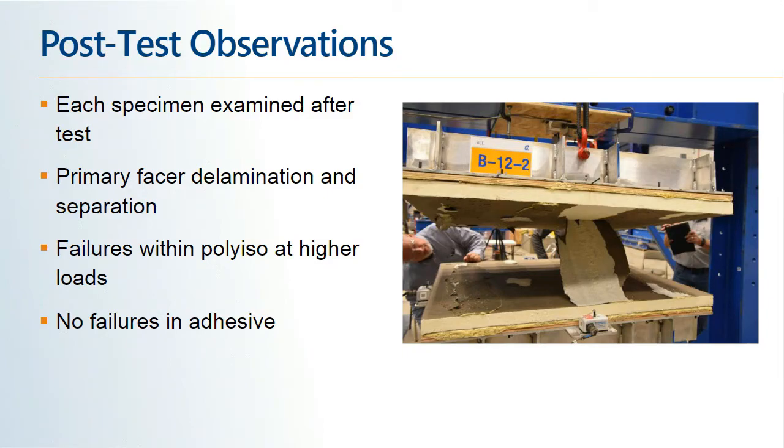lining up with my hand, you could see that the flattened low-rise foam adhesive ribbon remained in place, but the felt facer itself separated off of the adhesive, what we would term to be a cohesive failure plane within the cellulosic felt facer.